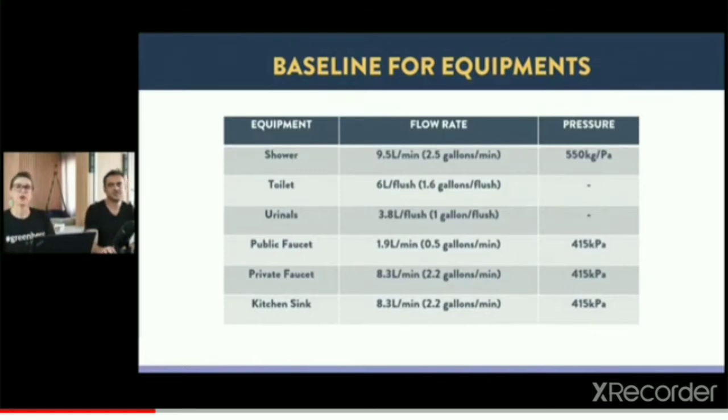When we're talking about toilets, nowadays most places have already the possibility of having dual flush with the same price as a regular toilet. Or you have the possibility of reducing, if you're using those toilets where you have the box right behind the toilet, you have the possibility to actually put an object there to reduce the amount of water that is infilling there.